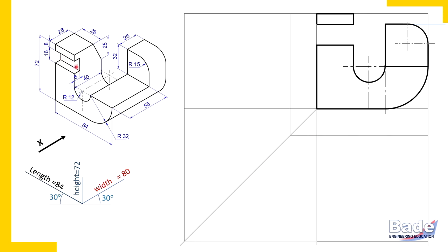It is partially hidden. This rectangular surface has a height of 16 millimeters. Watch here, it's given 16 millimeters here. And length 28 millimeters. These edges are 28 millimeters long. So this surface is partially hidden, but from the front it is completely visible. It has principal edges of 28 millimeters which we have already drawn. Then 16 millimeters vertical, one on this side and one on the other side. So those two edges, this is how we have completed that surface.